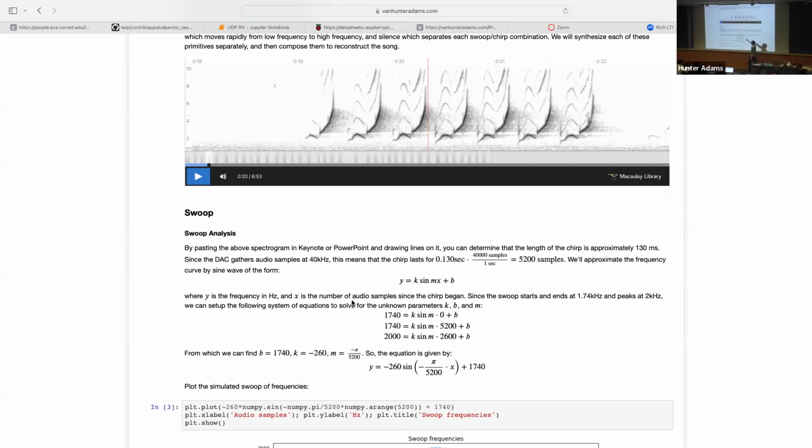By the way, I said that we want to compute this stuff as fast as possible. One way to produce this sine is with the math.h function, right? There's an inbuilt C library to produce sine. But didn't we just spend like 2 lectures talking about how to produce sine waves really efficiently? Right? So one might consider making one more DDS synthesizer here and synthesize that sine wave. Right? That's so much more efficient.